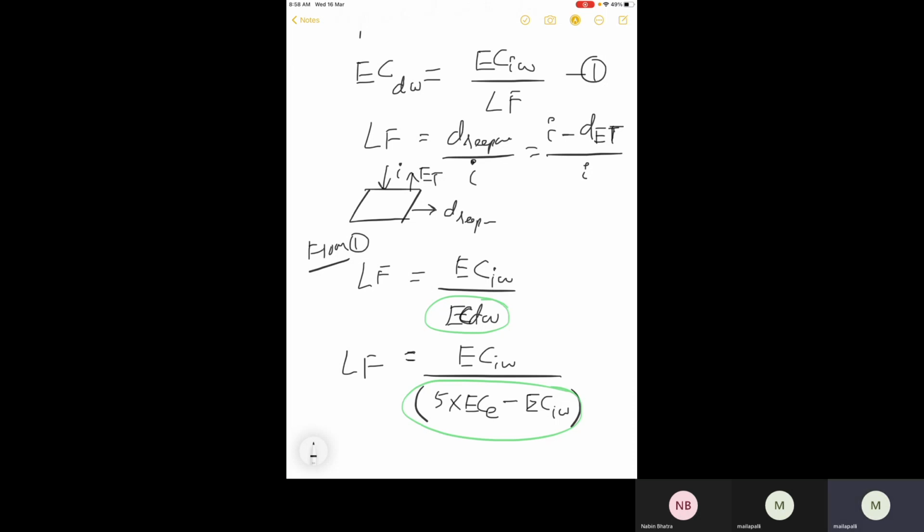You saturate it, and then you extract the water from the saturated mass, and then find out the electrical conductivity of that particular extracted water. So that will give you the soil salinity. Okay, that is ECE. So knowing that, and knowing the electrical conductivity of irrigation water, right, you can find out what is leachate or leaching fraction.